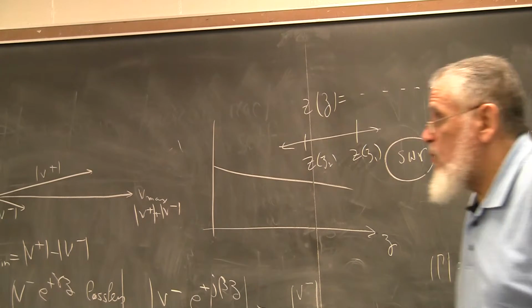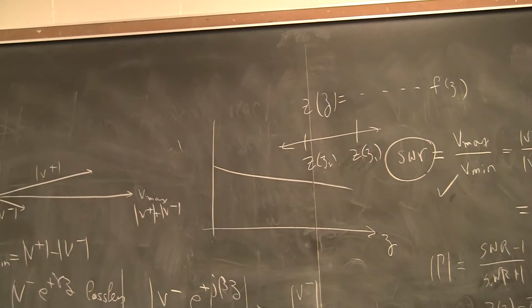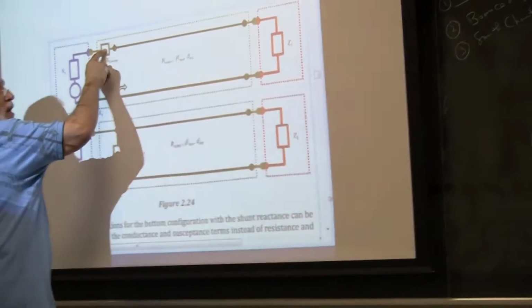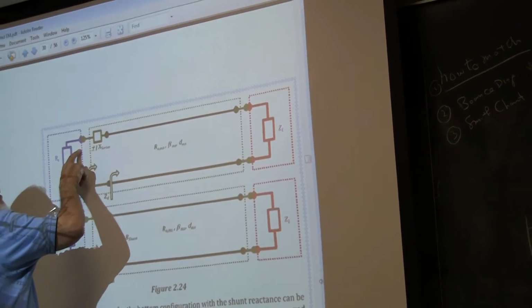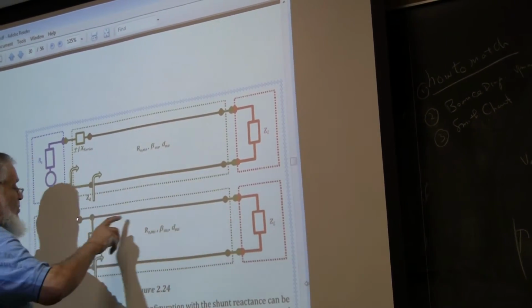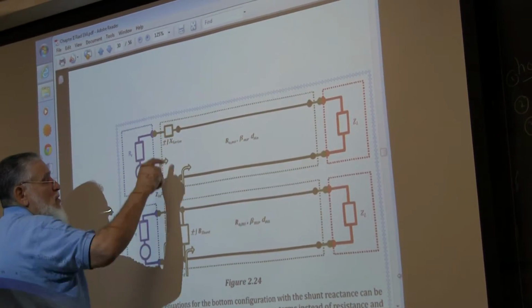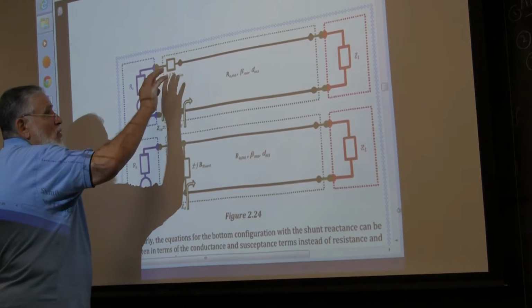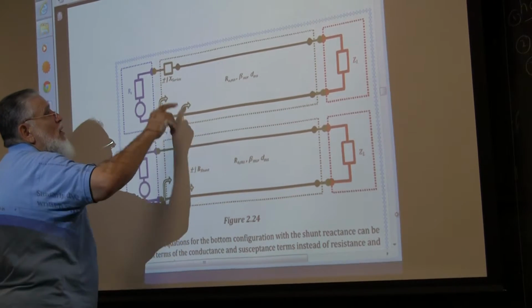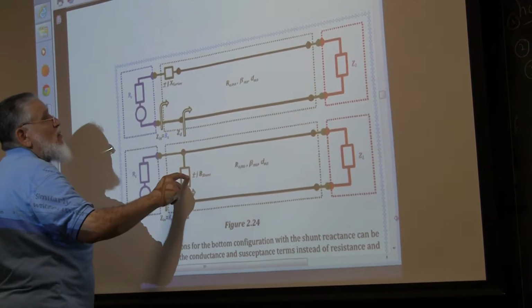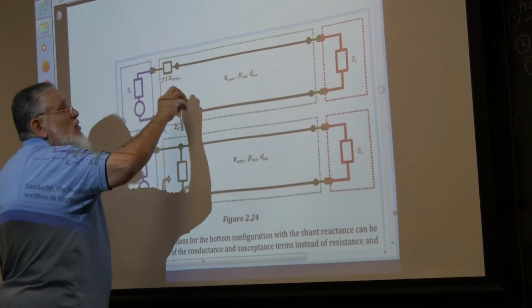So what we do is typically, that's a mismatched line, mismatched termination. I move down the line until I get close enough to the matching such that I add a reactance, and now I have matching. Can do the same thing by a shunt or a series. So I'm back to adding series or shunt elements, but not as the only element in the circuit. I'm combining that series or shunt element of reactance along with a piece of transmission line.